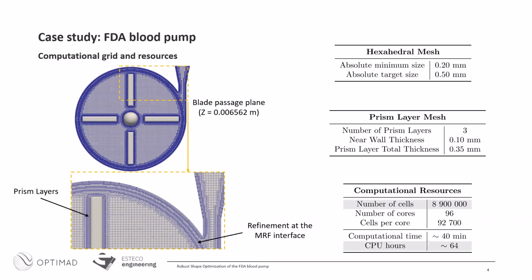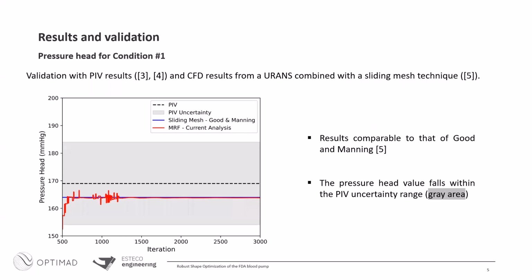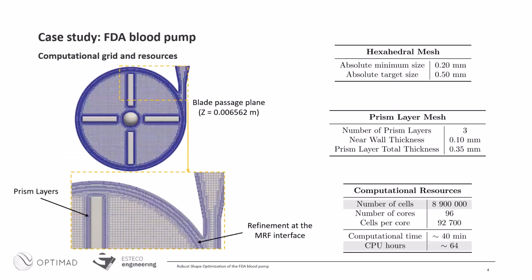We're using, for turbulence, the standard k-epsilon model. The Y plus was 50 more or less. But we also tested the k-omega SST model. Actually, as you know, it suffers convergence problems.